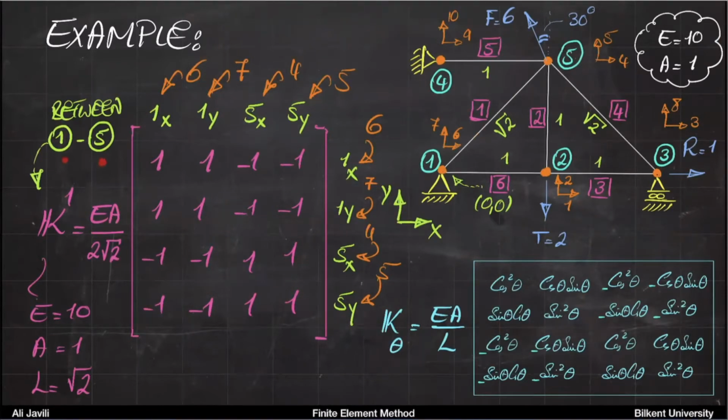element has its own connectivity. So for each of them, you can also think of it as basically the XY stiffnesses between the nodes at the two ends of each element. So if you think, for instance, of element 1, so this is element 1. Element 1 is between node 1 and 5. So the stiffness would be between node 1 and node 5. And then x direction, y direction, x direction, y direction, as we spoke before.